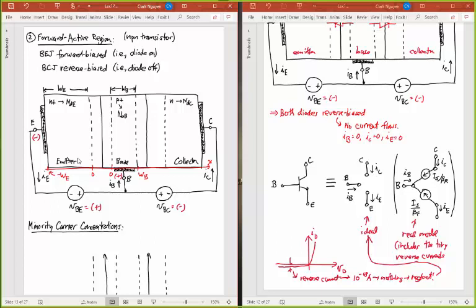And so when I make that negative, effectively, wait, VBE is positive. So the collector base voltage I want to make negative. Making VBC negative means making VCB positive, which means effectively I'm putting more positive charge here than I have on the base. So in that way, I am reverse biasing this diode. Okay, so this diode is reverse biased.